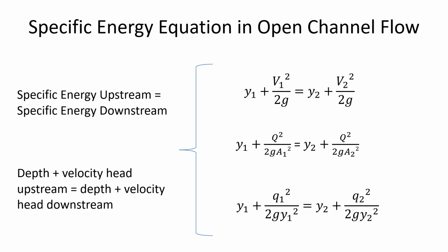Just think about water flowing through a river does all sorts of irregular things. It's only prismatic channels that are engineered where we're likely to see Manning's equation over any kind of a long distance. Maybe we'd see Manning's equation over a short distance in open channel flow that's natural. In any case, we're using specific energy equation.